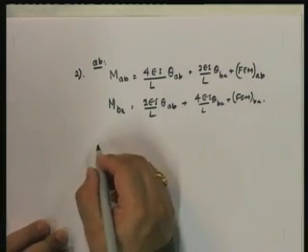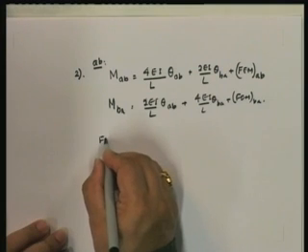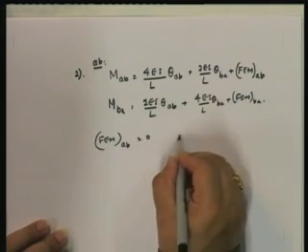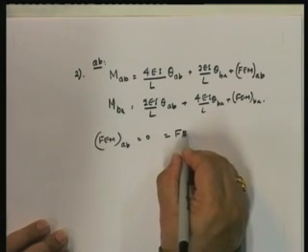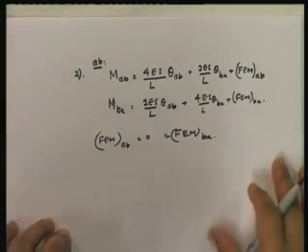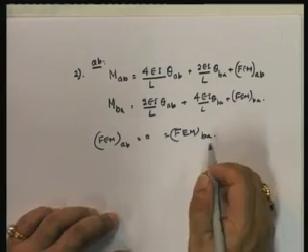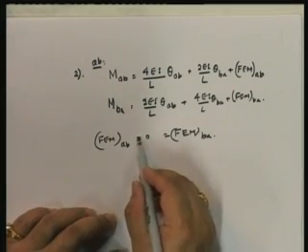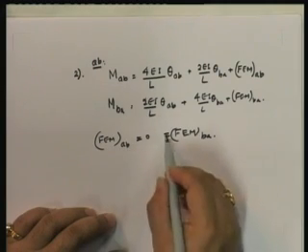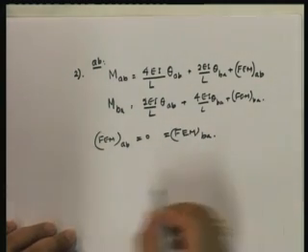Now here, what are the fixed end moments? Fixed end moment of AB is equal to 0, which is equal to fixed end moment of BA. Why is that? That's because there is no member load on AB, and since there is no member load on AB, fixed end moments are automatically equal to 0.